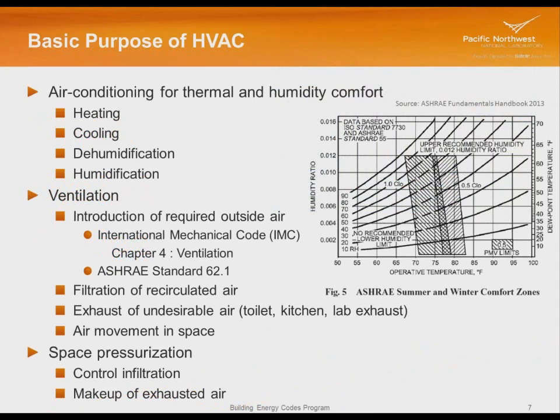So what's the basic purpose of an HVAC system? Well, first of all, we have some air conditioning for thermal and humidity comfort, and that includes heating, cooling, dehumidification, humidification. If you look at the little chart on the right, that's the ASHRAE comfort diagram, and you can see that there's two areas of comfort related to clothing.